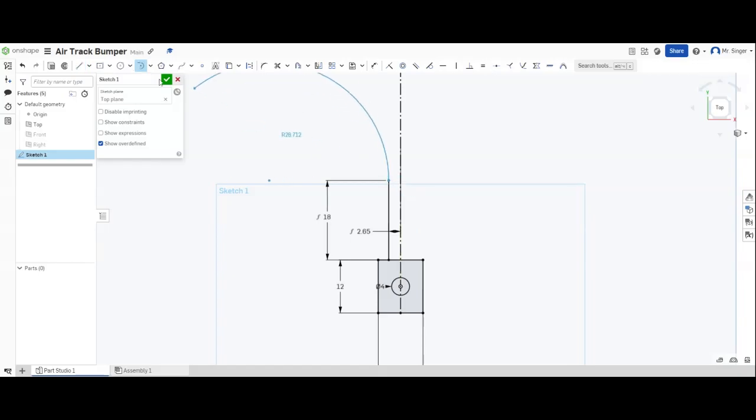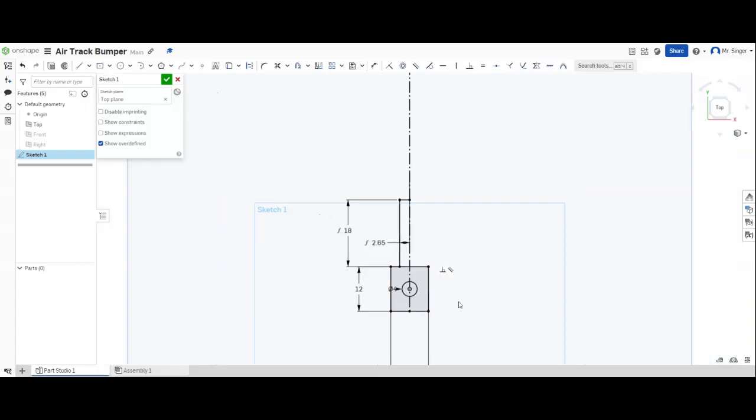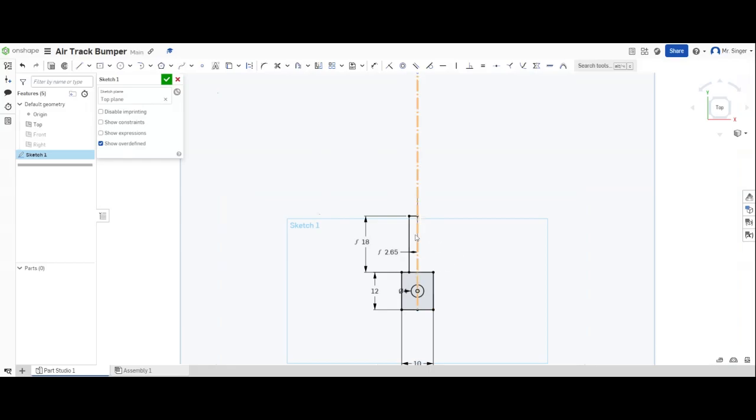Now I'm just going to close the shape. I don't know why that tangent thing happens. Wish I could turn it off, but anyway, you come over here to the line and you just close the shape to the center line, and you deselect the line implement. And now what I've done is I've only created half of the stem.